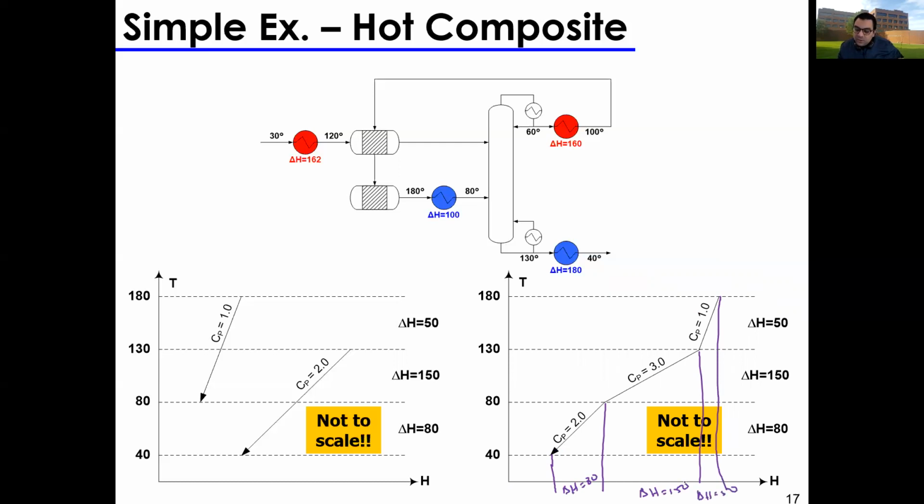And it's important to note that this bottom, of course, you can start from 0 if you want, but this bottom doesn't really have any points. You can add a reference point, which is 0 to everyone, but you need to understand that heat exchange is a relative quantity, right? So you can always add a reference point for it to make sense. And of course, if you're using graphing sheet, using Excel or whatever, you should always add a reference point, okay? And this is the approach we're using, and this creates this curve called the hot composite curve.